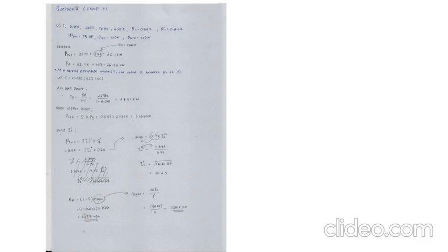Okay, after calculating all of the power and losses, we need to calculate the value of I using the formula P_CU equals 3 I squared times resistance, where the copper losses 1.164 kilowatt equals 3 I squared times 0.24, where the value of I we need to find.